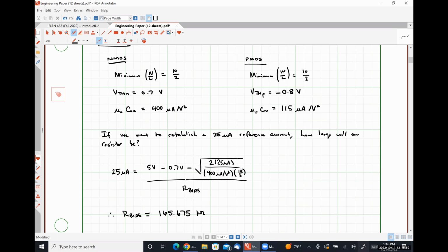It works great for discrete level things. Not really great, but it's the thing that makes the most sense because you cannot guarantee transistor matching or anything like that. So making a discrete component amplifier using resistors makes sense. You have a lot of control over what the values are. In an integrated circuit, you don't have nearly enough control to make sure that this particular resistor value stays the same under all of the different operating conditions that you might be in. So problematic at best.